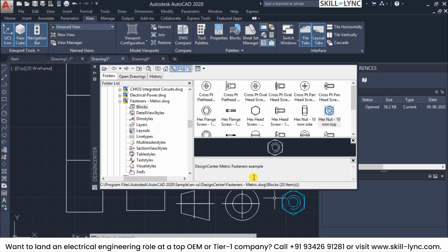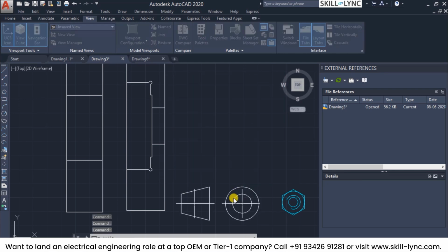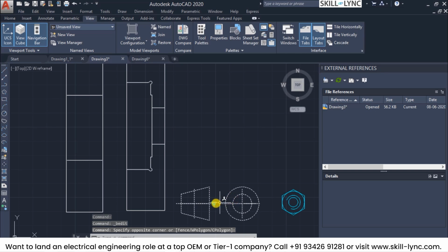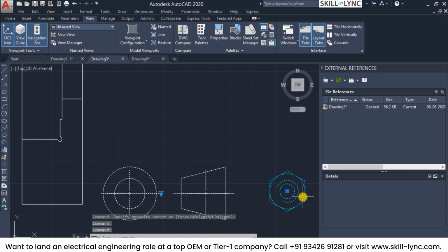So here, as seen, you can use the search option to look into the metadata information rather quickly. Once having inserted the block into your definition, you can see that all the original properties of the block get written. Here, based on the visibility that we have designed, we can select it out. Typically this block doesn't have any dynamic references, but the drawing that we had created had them, so you can use those customized drawings in your original drawing.